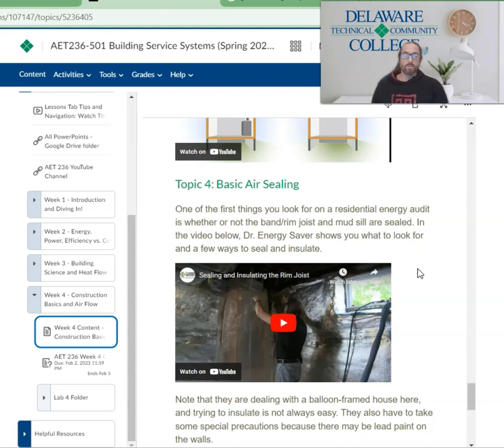And so as you should know, if a cubic foot of air goes out of a building, a cubic foot is coming back into the building, and you can't stop it. That's physics. If you have something like the stack effect, which is pushing air up and out of a building, at the same time it's pulling air in, usually toward the bottom of the building. I'm posting this video at the end of January in the Northeast, so it's cold outside. And it's difficult to stop the stack effect.